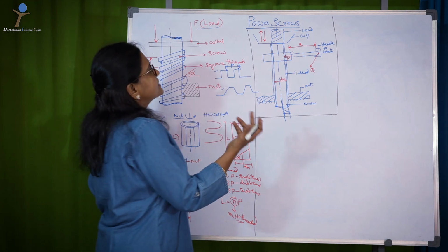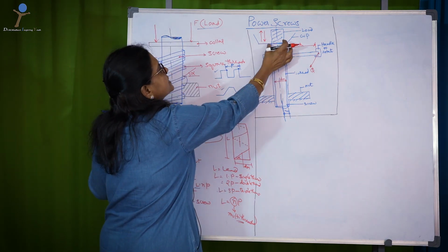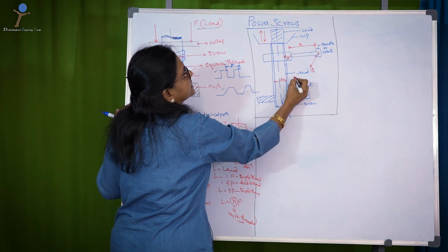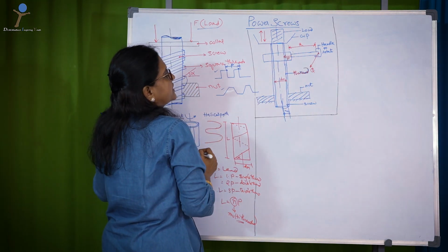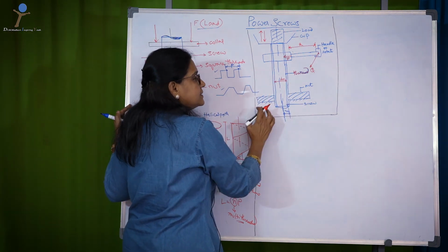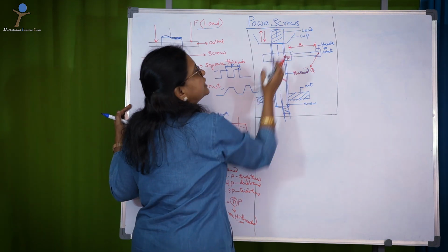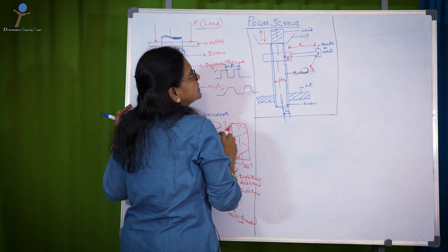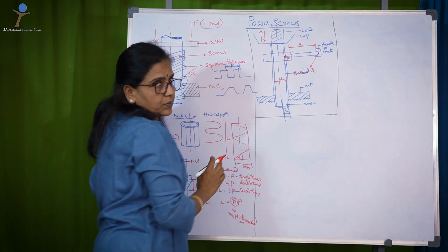Now, let us clearly understand one screw jack mechanism and then try to go into the mechanics part of this. So, as I said, the power screw or application as a screw jack will comprise of a screw thread. This is a screw rod and this is the threading part, internal line that I have given, which is having a diameter of dm. This is the nut. Assume that it is fixed. Then you have a cup-like arrangement so that you can place the load that can be in tons, can be placed here. Now, the objective is to raise this load up or down.